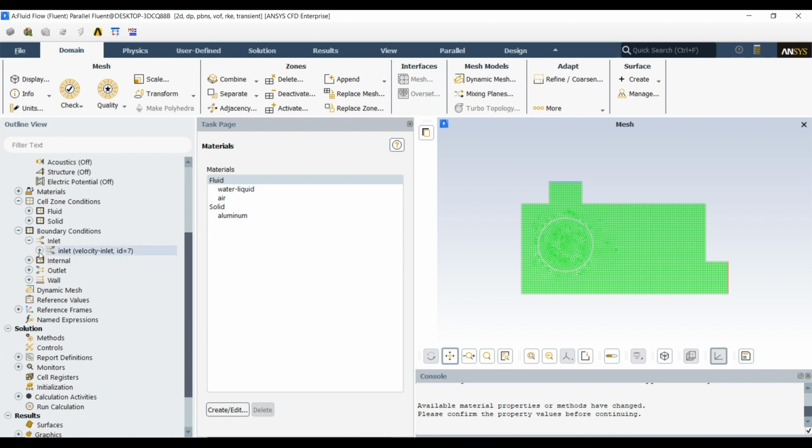So in this case you will make sure that you are having only water spraying from the inlet. If you have a different case, you can do 50-50 or whatever volume fraction is proper for your problem. So I think that's all for the boundary conditions, I have just one inlet. The outlet is defined automatically because we named it outlet. It's a pressure outlet.